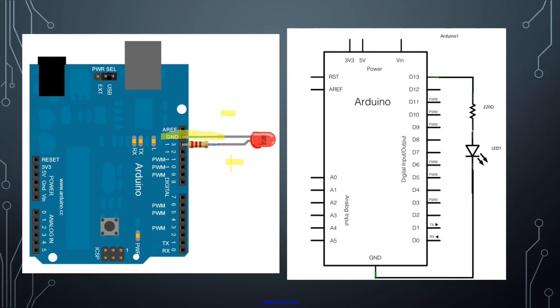And then to the positive side of our LED, we'll want to connect a resistor. And then that resistor will just be connected to a pin. So we can connect this to any pin, barring limitations on the pin, right? I talked about how only certain pins are analog pins and so on. So within reason or within certain limits, you can connect to any pin or a variety of pins.